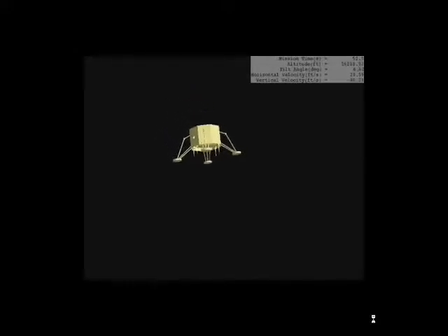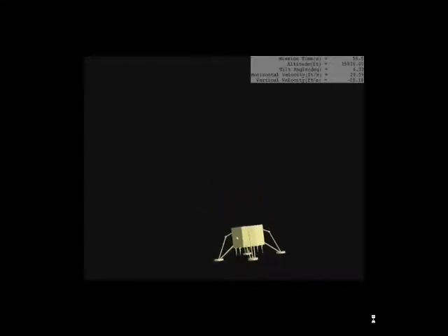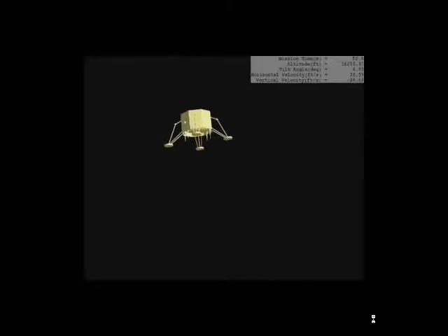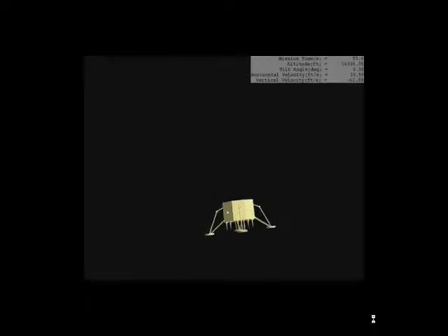When the vehicle's horizontal velocity reaches 0, the Star 27 separates and thrusters on the motor accelerate it quickly away from the lander. The gas generator on the lander is immediately ignited and the lander reorients to perform a correction burn. The lander adjusts for any ground range error due to variations in the Star 27 performance. In this idealized example, the error is minimal, so the propellant in this pulse is used mostly for attitude control and not for braking. The lander drops toward the Moon's surface.